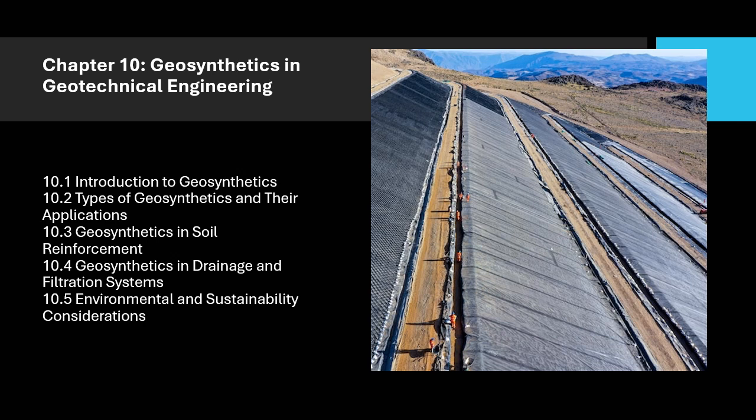Description. Geotextiles are permeable fabrics made from synthetic fibers that are used primarily for separation, filtration, reinforcement, drainage, and erosion control. Applications. Separation layers between different soil types to prevent mixing. Filtration and drainage systems to prevent clogging. Reinforcement of weak soils or subgrades in roads and embankments.